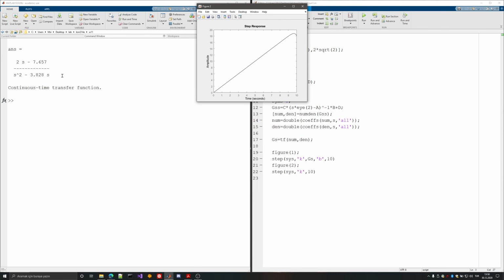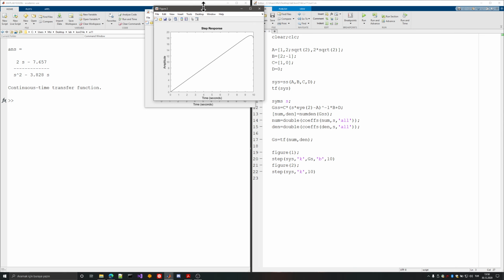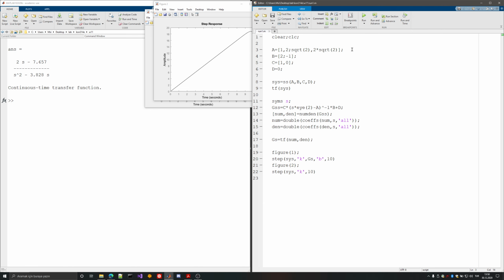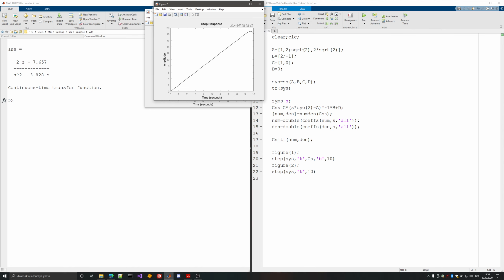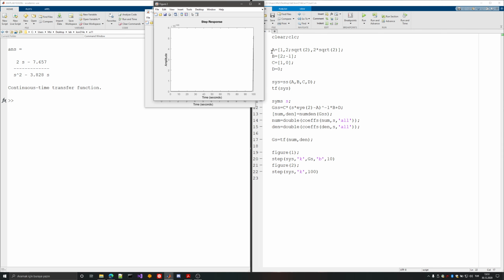And this also shows you the importance of knowledge in terms of theoretical basis, because if you are not aware of the deficiency, if you don't see it, then you might ask yourself why this is the result, because this is basically an integrator with gain 2 and nothing else, but you get a fading response, which shouldn't be the case. Let's give it, let's say, 100 seconds. After 100 seconds it becomes unstable, but it's the reason why, because of numerical problems.